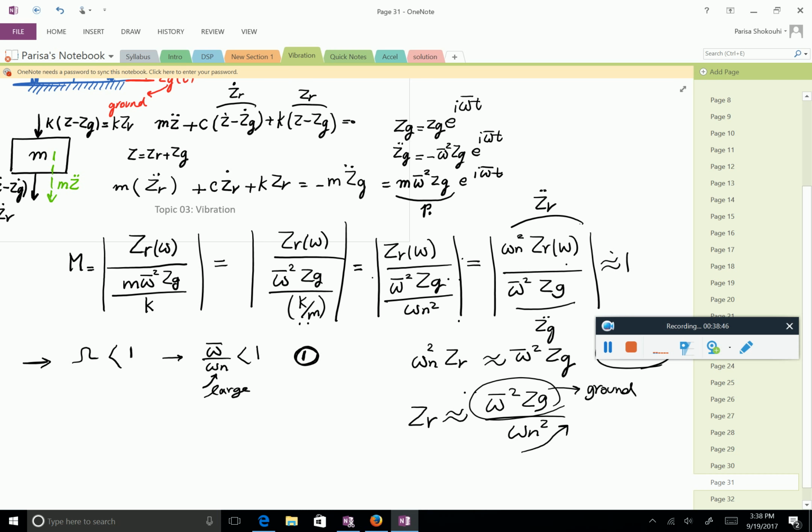So you want your accelerometer to have a large natural frequency, but not too large, such that it compromises its sensitivity. If the natural frequency is very high, no matter how hard you vibrate, the accelerometer just shows a little bit of movement. It doesn't even see it. You don't want that either. So these are the principles of the accelerometer.